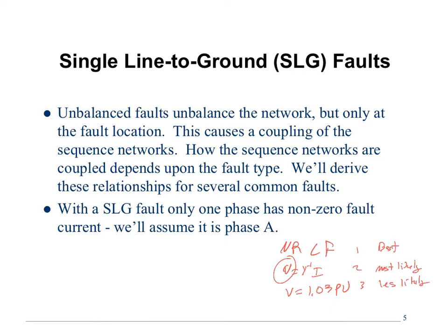and fairly conservative. So this is very important. Make sure you know which one you're starting with. So if a customer says, hey, I want to calculate fault currents, you need to figure out, am I modeling it from a V equals Y inverse times I? Do I have enough information on the loads in my system? Or will I just use a flat start? Okay? This one is if you're using Aspen and you're modeling the transmission line.